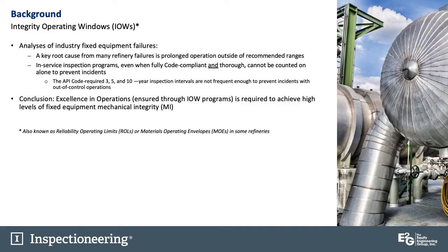Anyway, regarding IOWs, analyses of industry fixed equipment failures have identified that a key root cause for many refinery failures is prolonged operation outside of recommended ranges, and that in-service inspection programs, even when they're fully code compliant and thorough, cannot be counted on alone to prevent incidents.